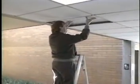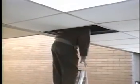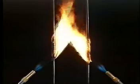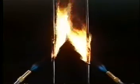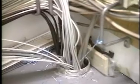In many indoor situations, fiber cable will be installed in plenum areas, often above acoustic ceiling tiles or below raised computer flooring. Plenum areas allow for air movement in building ventilation, so national building codes are very strict as to the type of materials used in communication cable. Most of the codes are concerned with the cable's reaction to heat and the production of toxic smoke. Most countries have established national electric codes concerning indoor electrical construction. In certain situations, local regulations supersede national codes.